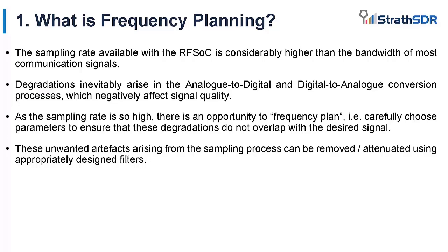Therefore, there's a motivation to do frequency planning. In other words, to make sure that none of these artifacts and degradations overlap with our desired signal. Any unwanted artifacts which are captured by the sampling process can later be removed or attenuated using filters.